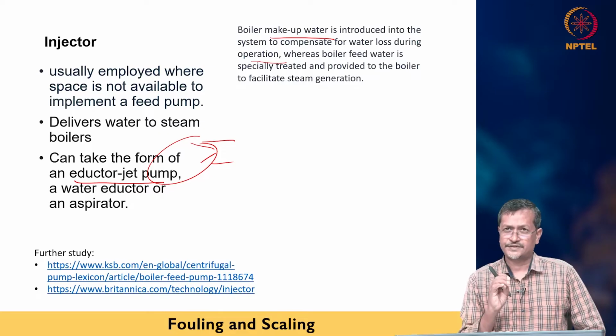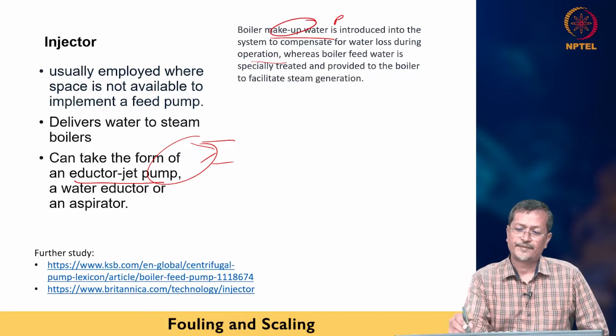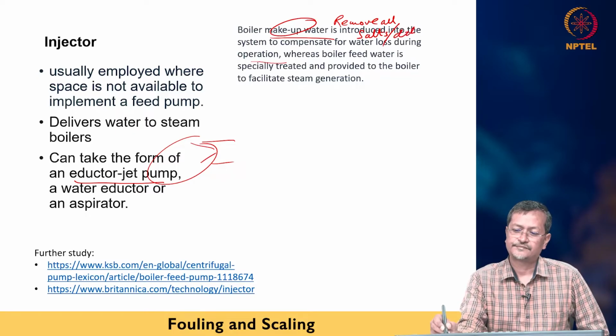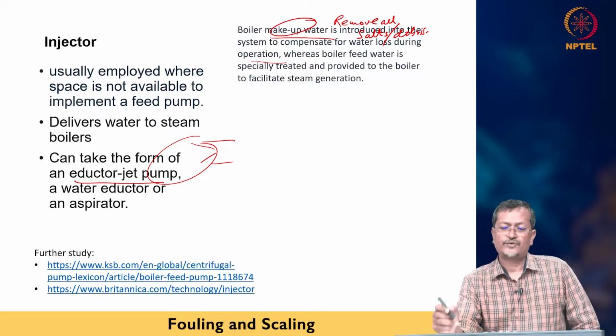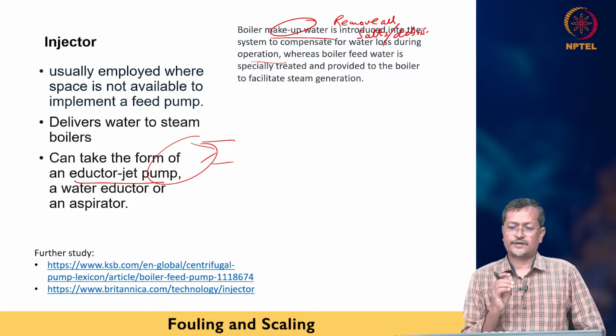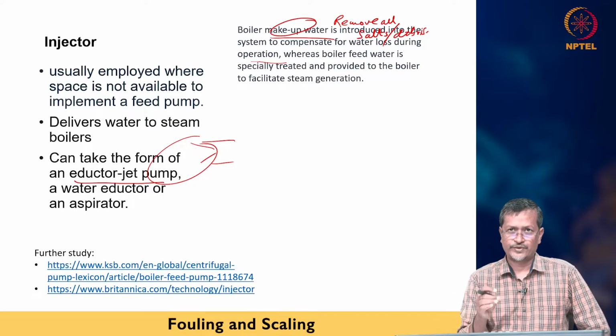And makeup water means you cannot give seawater. You have to remove all salts and debris, then inject into the boiler. Because if you give water with salt or some other debris, it will get deposited in the boiler pipes, and at a later stage it will create problems. So whenever the makeup water is fed into the boiler, the water must be distilled properly.